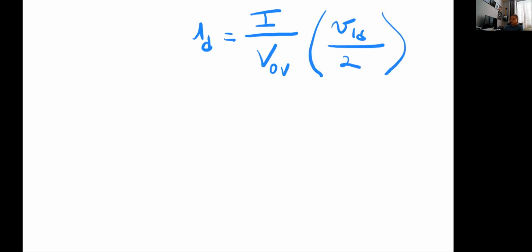So the differential current is proportional. There is a proportion formed by half the differential input voltage to the overdrive voltage. All right. So let's do a small signal operation based on figure 9.8 that I showed you.